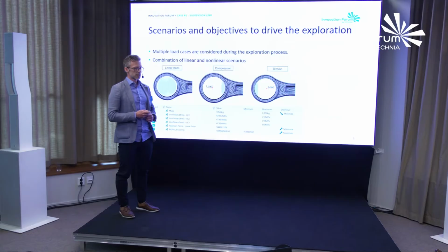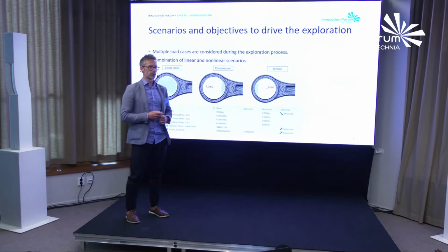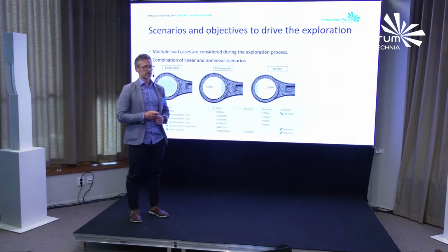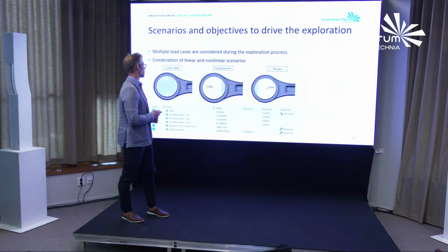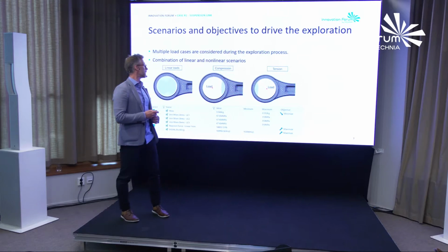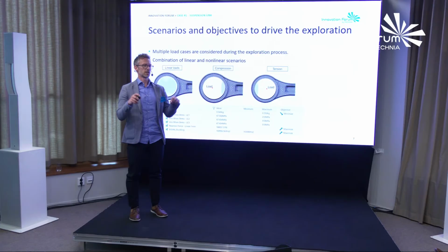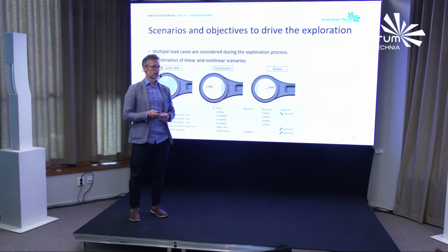For the load cases, we have 3 linear load cases that come from the OEM. It's more or less forces and moments that are applied on the bushing. Then we have the compression load case, which is to try out eigenvalue buckling. And the third one is linear and nonlinear tension, so just pulling it and checking the limit for tension.